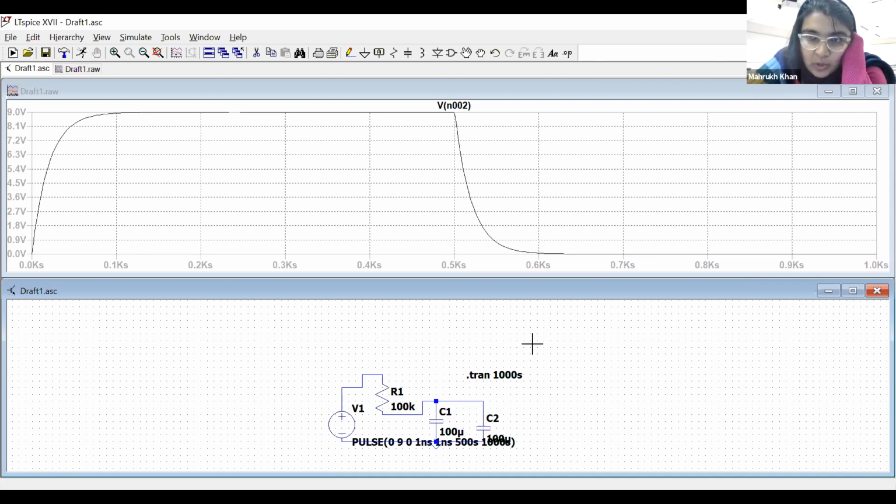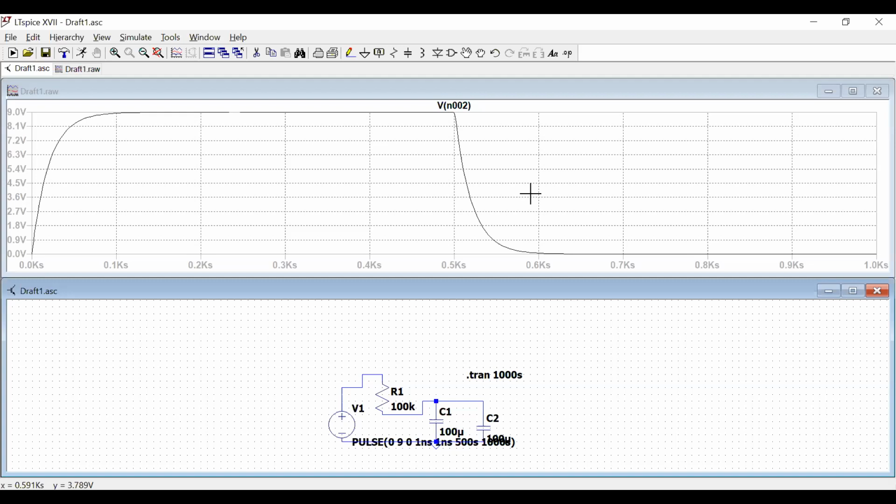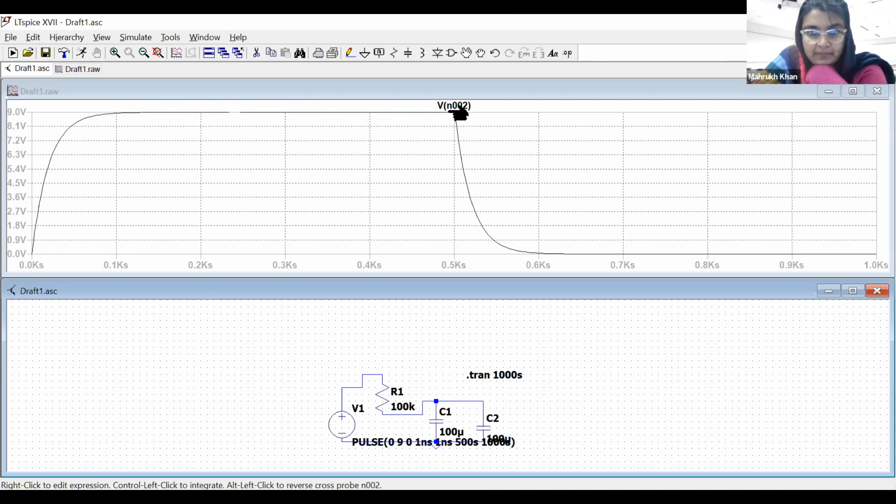Okay. Anybody knows what is this transient time here and what is the steady time here? Is the transient time up until the curve flattens? Yes, which is 0.1 ks. So the transient time is this one, because here you can see the change is happening. And steady time is this one, where it's at the same point as your capacitor voltage, right? Understand?